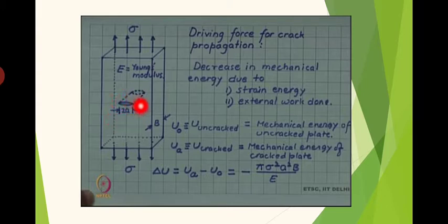Anyway, if it is an interior crack, the size of the crack is expressed as 2a. If the size of the interior crack is given, then we have to consider half of that as a. If it is a surface crack, then you can take the given value directly as a. Since I am considering an internal crack here, I have specified the crack size as 2a.